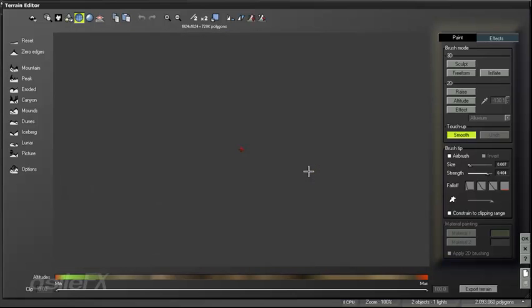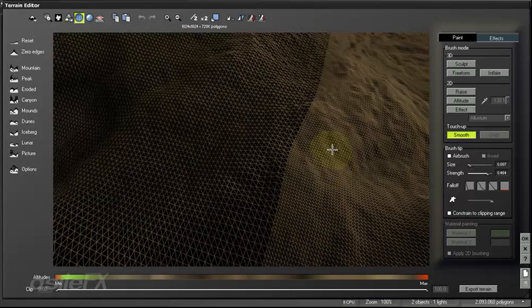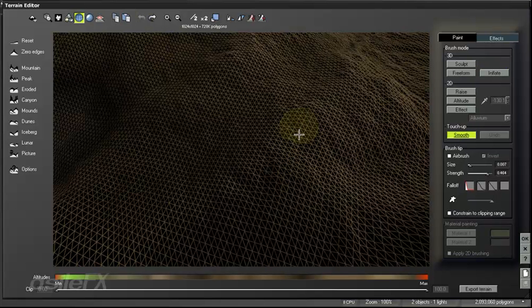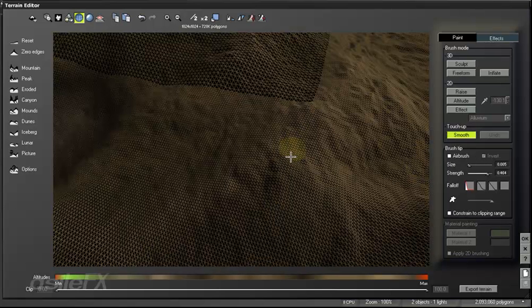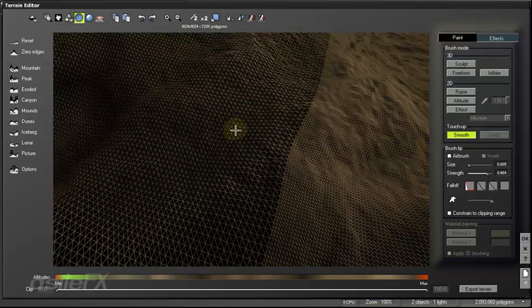If you just can't afford to have that much geometry in the scene, if you've got a lot of other objects, one thing you can do to cover up the seam, besides putting the object underneath, as I had showed earlier, is you may be able to pinch it together, because simply smoothing it isn't going to work, because those points just aren't connected.